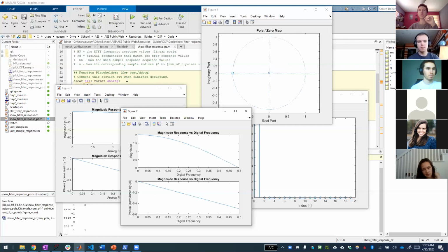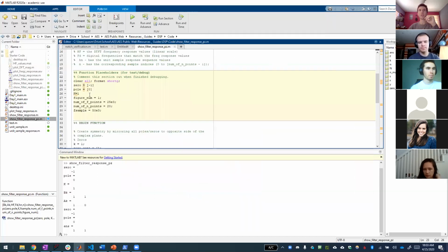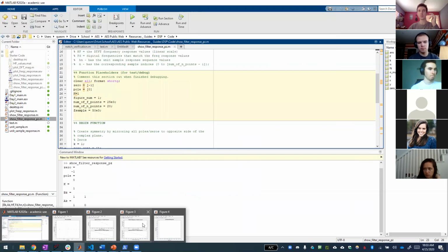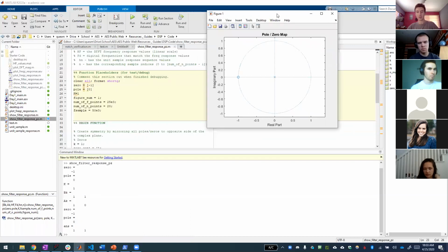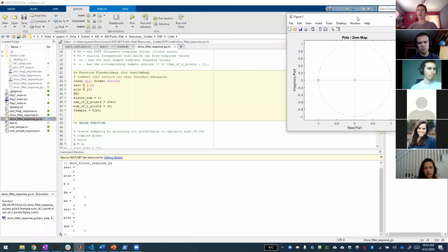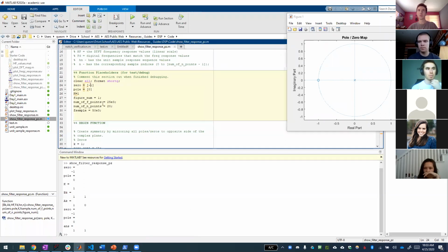So then I guess if you wanted to make a high pass, oh, that's what I should have pulled up earlier. It's just this. If we wanted to make a high pass, the idea is we don't want to disturb the high frequencies. We'd want to get rid of all the low frequencies. So we can move the zero to the other side.